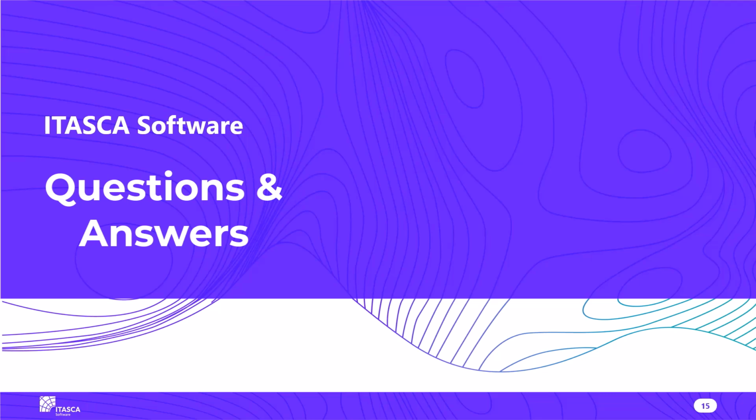And then the second half of the question I'm reading in the Q&A here is, you could, in theory, take one of those models and modify it to work for Hoek-Brown or add viscous elements to Hoek-Brown. It would be a little effort, but you could probably do it. And to clarify that second part, the question is, are there built-in options or supported user-defined models that allow you to introduce viscoplastic or strain hardening formulations? I'll just add that the plugin or add-on to do your own custom user-defined models used to be an option that was an additional cost, and we now include that for free as part of the base package.